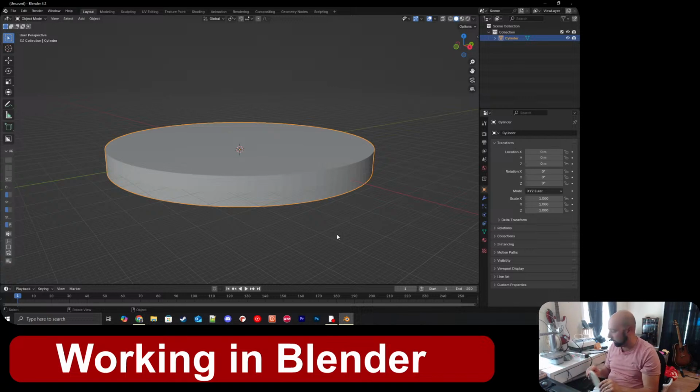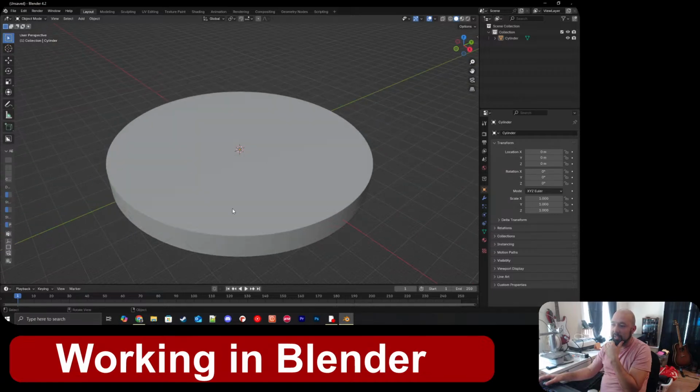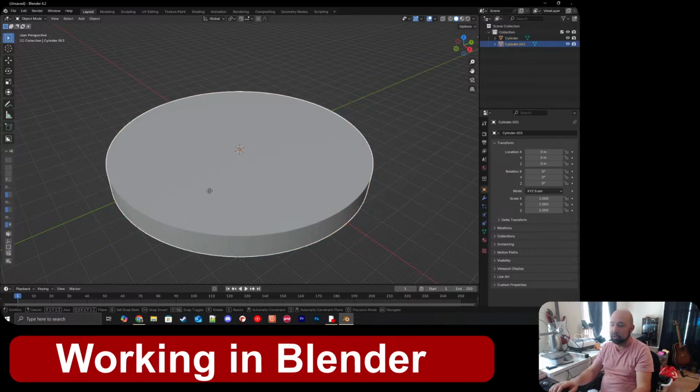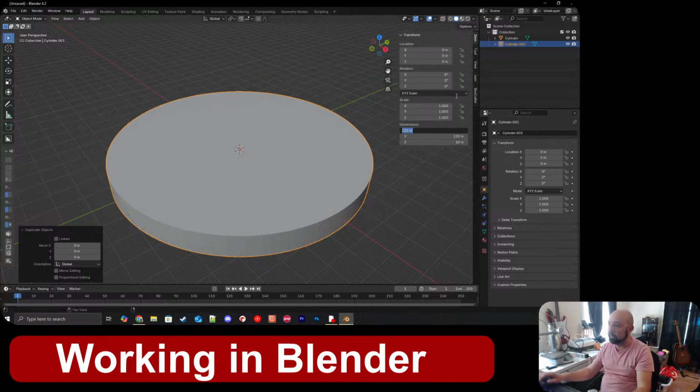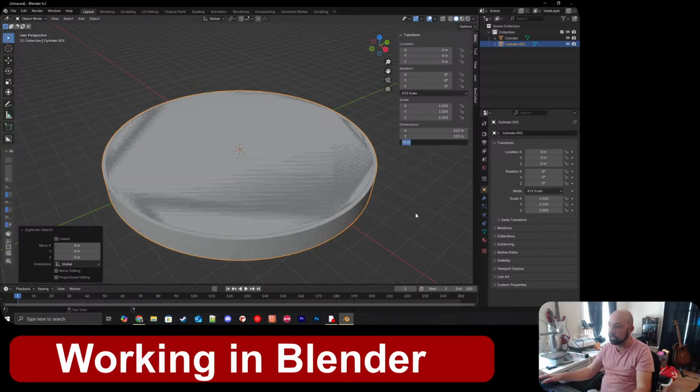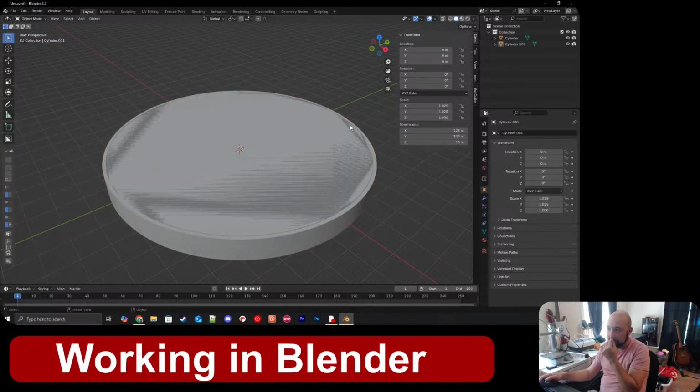So we need to hollow this thing out. I think it was hard to measure the thickness of this stuff. I'm going to call it 1.5 millimeters thick. So this is the actual size of the bowl. So I need to make something that's like 3 millimeters bigger than this. Let's just Shift D to duplicate that, and then we'll go to the properties. We'll change this to be 123. So that's like the size of the lid there.